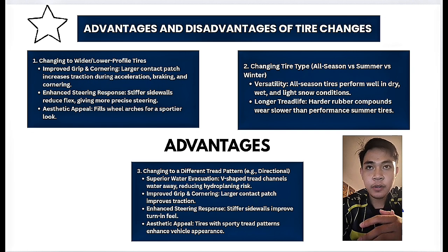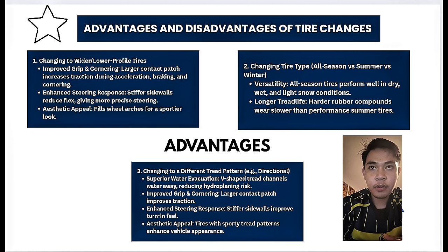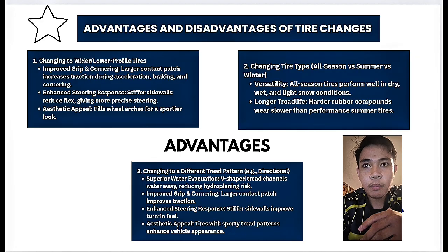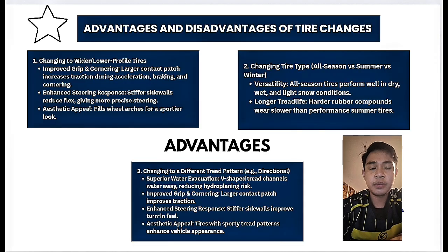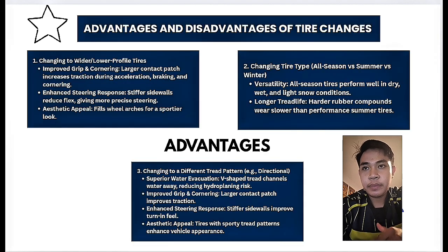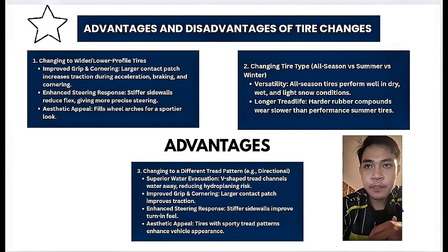The advantage for changing tire type is versatility. All season tires perform well in dry, wet and light snow conditions. Next is longer tread life. Harder rubber compounds wear slower than performance summer tires. The advantage for changing to a different tread pattern is superior water evacuation. V-shaped channels push water away, reducing hydroplaning risk.